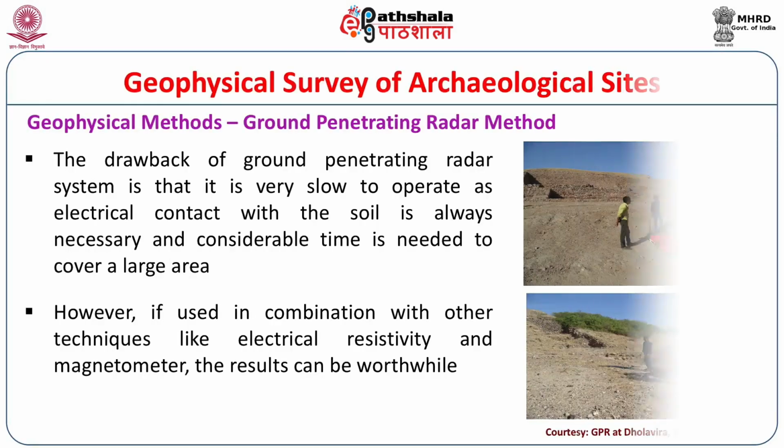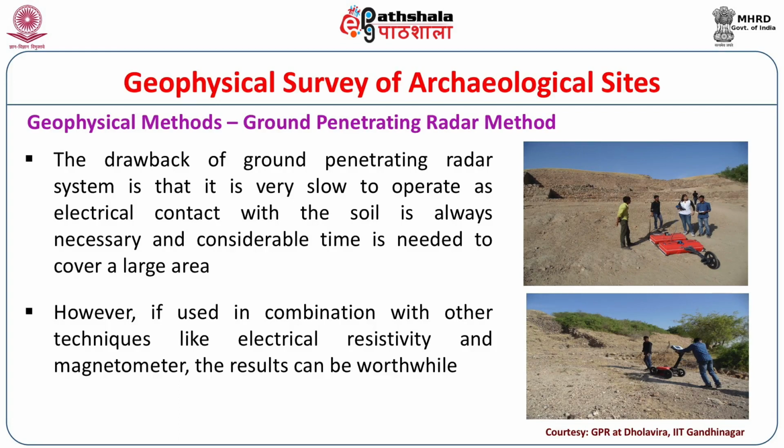One of the drawbacks of ground penetrating radar is that it's very slow, because it has to be moved very slowly on the surface where the investigation has to be carried out, and a few people are required for moving the antenna, pulling it, and carrying the on-field monitor. Also, if we want to make a very detailed 3D reconstruction, a grid pattern has to be developed, and we have to move the radar or the antenna in a crisscross manner. So it takes a lot of time.